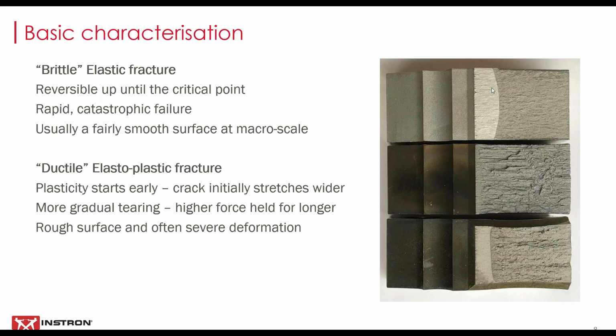But once you get to that critical point, that critical amount of stress at that corner, at that notch, the failure is rapid and it's catastrophic. That crack is going to start running, and it will run. In a specimen, it might be centimeters. In a large structure, it could be many meters.